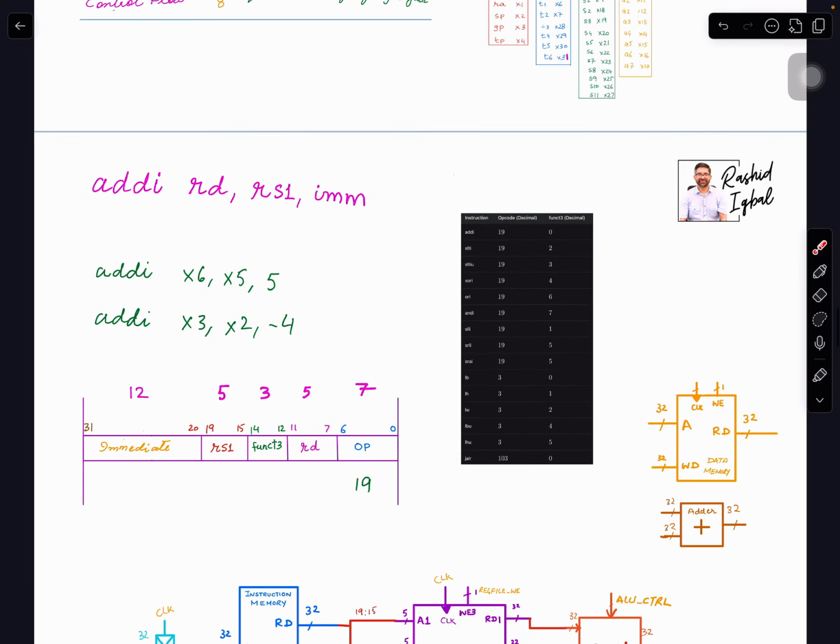So our PC, because we initially pressed reset, or we started the SOC, is at what value? This value. We can initialize it with a different value too, but right now we are assuming our code starts at 0, so it will have this address. So what happens as soon as this address appears, we immediately read whatever was at this address, and I'm assuming it's this value here.